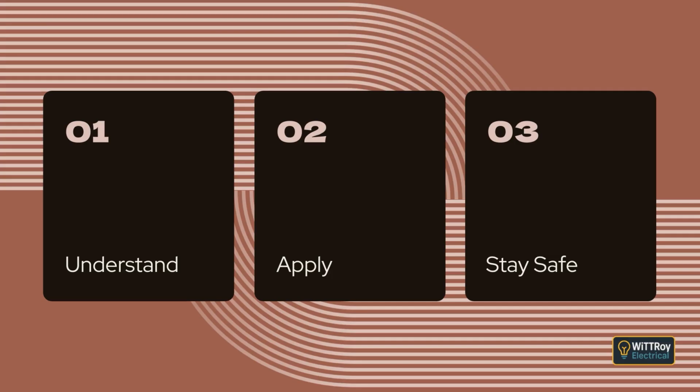Clause 3.3.2.8 Other mechanical stresses. This clause explains that wiring must be installed so that stresses do not damage the insulation, sheathing, or connections throughout the life of the installation. Damage can come from weight, movement, bending, or pulling forces.